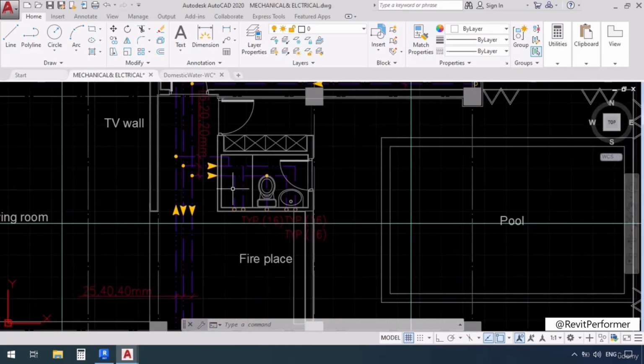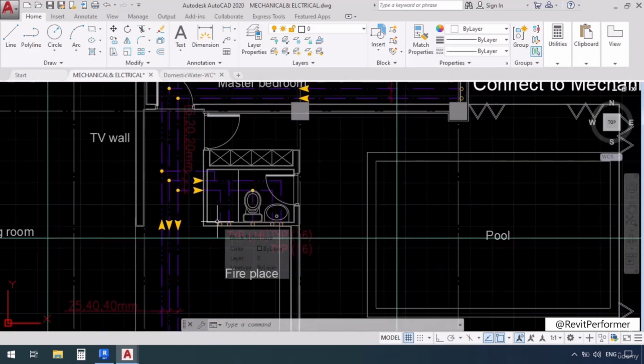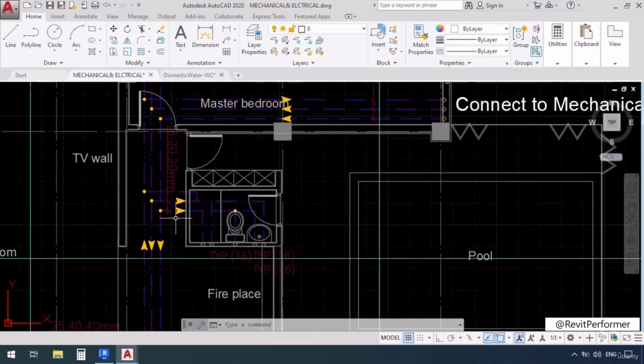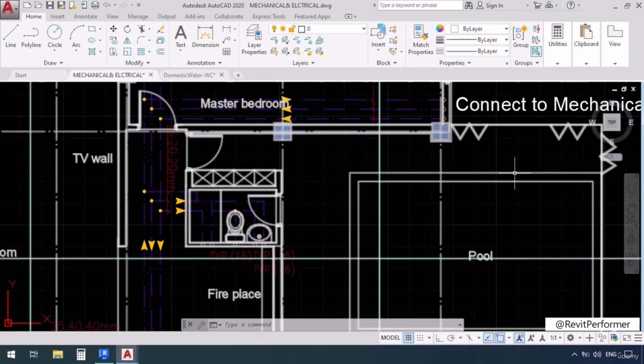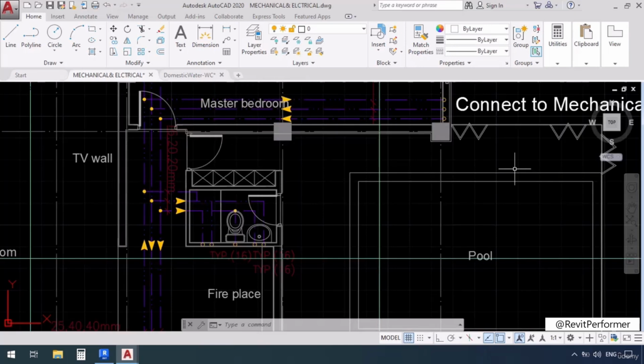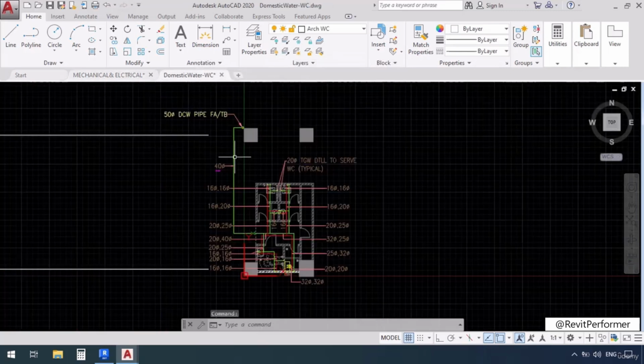It comes in here and into this stall and through the faucet. Then we also have the hot water supply, which is coming in from this way and again ends at the same faucet. There's also a branch coming out of this hot water supply pipe, which continues to the hot water return pipe and eventually returns back to the mechanical room. Actually, we're going to need this hot water return pipe because we're going to need to maintain our temperature. So there goes one plan type. We're going to go back here to take a look at another one.